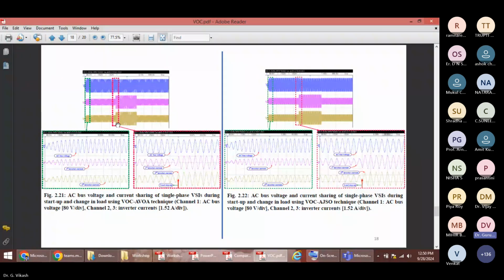From my understanding, in grid-connected mode, our present power system is already dominated by synchronous machines, so grid-connected operation is very easy. All our inverters are directly connected to the grid. If the grid is on, they inject some active and reactive power into the grid. If there is no grid, they sit idle and do not do anything.